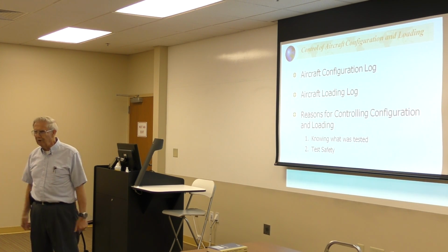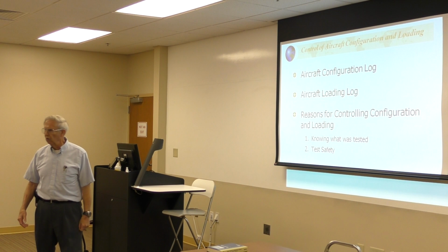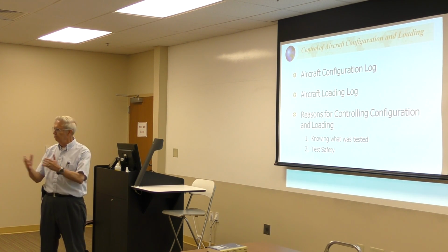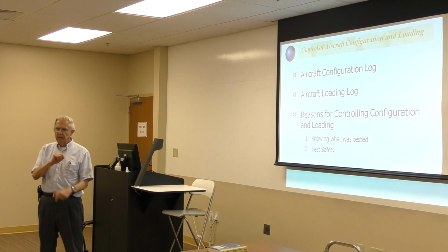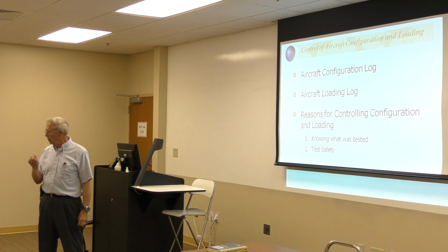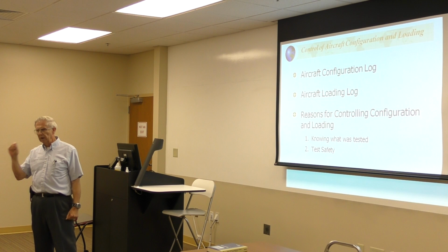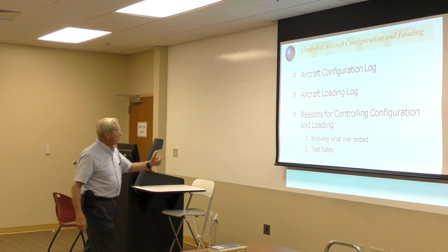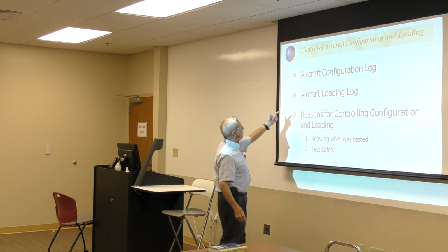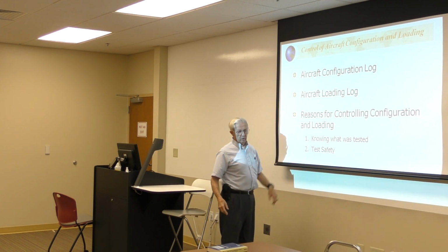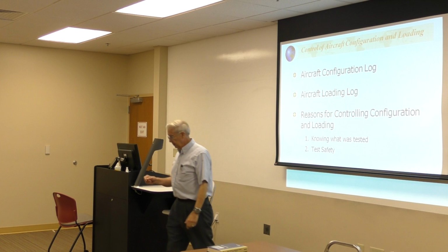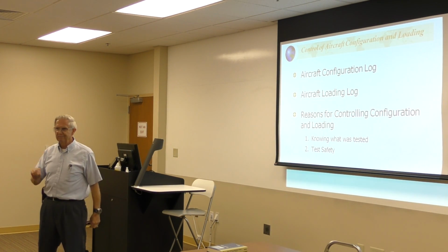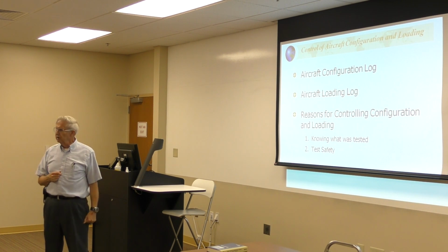So you have to have what we call configuration control, and the way I've generally done that over the years is make myself a logbook that for each flight I put what the configuration was, what the loading was, and correlate these two with a loading log, and for, say, loading number 3, configuration was number 6 or whatever, and number them, just so you can keep track.